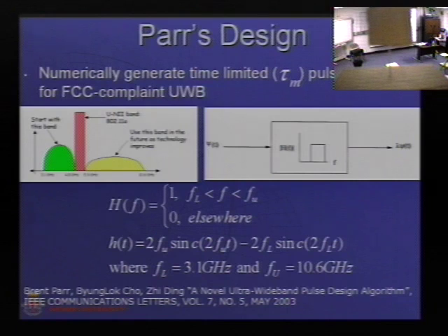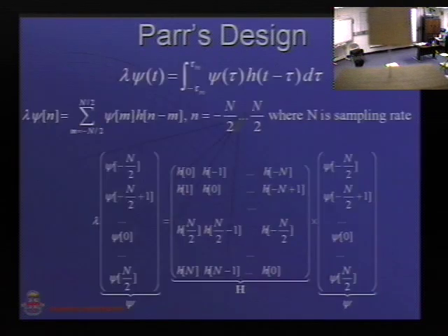How do they do this? You can transmit all the information, now I design a band-limited filter. Only let the information through at the lower stop band and high stop band. In the frequency domain, you allow this FL, say 6 gigahertz to 10 gigahertz. Then in the time domain you just do the numerical opposite, then design this waveform. Basically you need to solve this matrix. This is a waveform eigenvalue problem. This T is your eigenvector corresponding to your waveform.